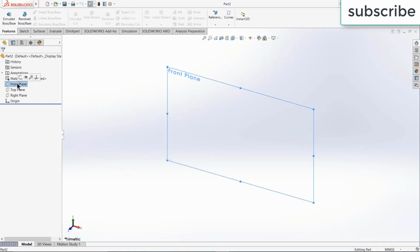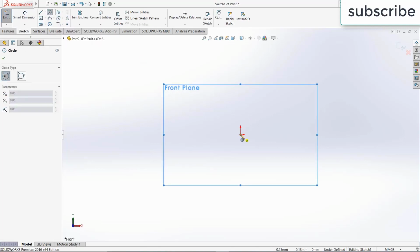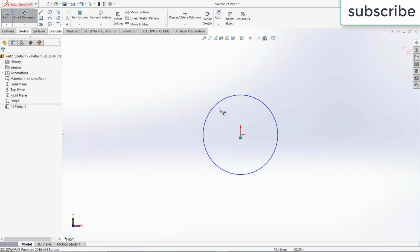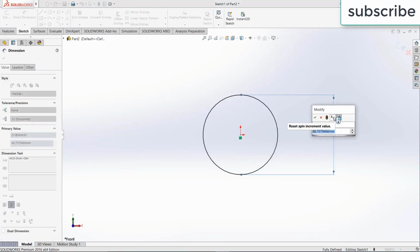So first of all, select the front plane, click on sketch. After that, first thing we are going to do is make a shaft. So select a circle, draw a circle. Now give it a diameter as per your shaft requirement. Let's say 90 mm, or 90 mm is too big. Let's say 40 mm.